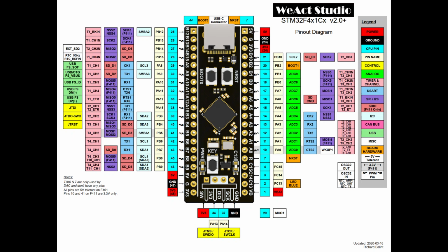A channel is a way to organize the pins and timer functions. Typically, each timer has up to 4 channels distributed across 4 unique pins. If you choose a different pin, then a different channel and timer is associated.